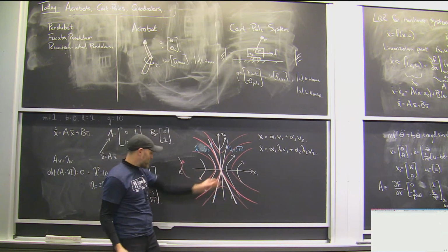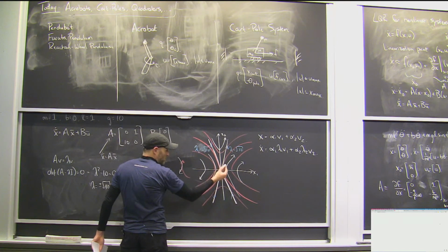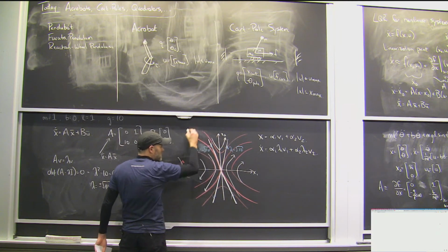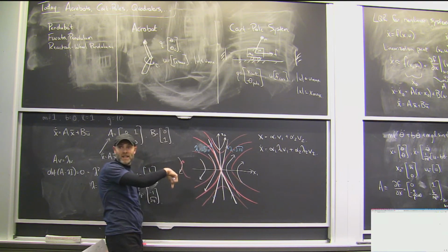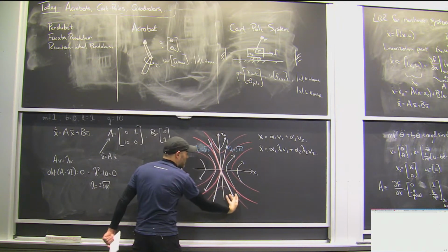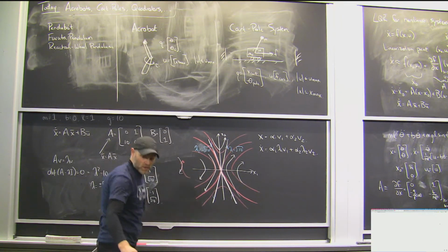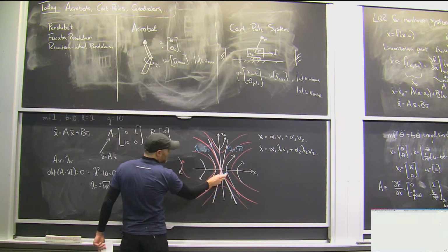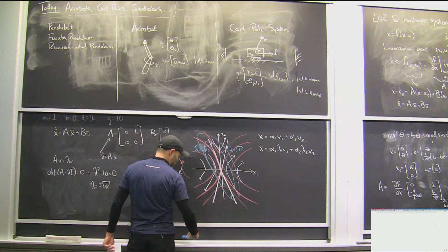So you can imagine now that if I were to take my linear optimal control toolbox and apply it to the linear system, if I called LQR, for instance, I'd get a linear feedback controller and a quadratic cost to go, which guess what, is going to be elongated in this direction, exactly like we saw before, where the direction you're riding in your momentum, your cost to go level sets are going to be stretched out in those axes and sharper in this axis. And you'll get a cost to go function that understands somehow the dynamics of that system, at least locally.